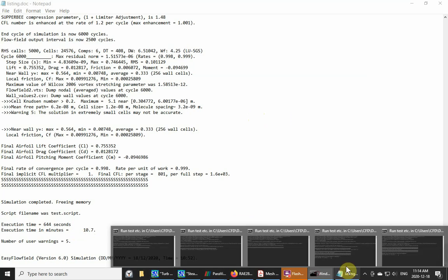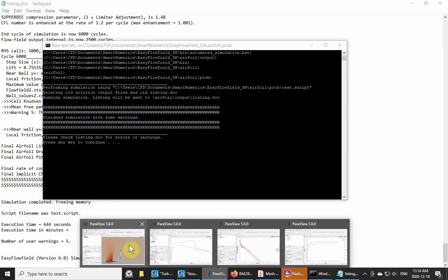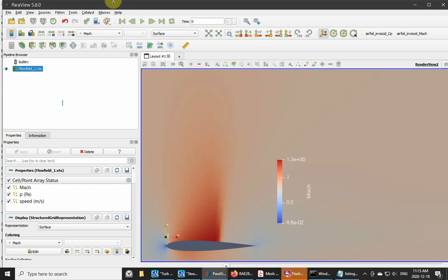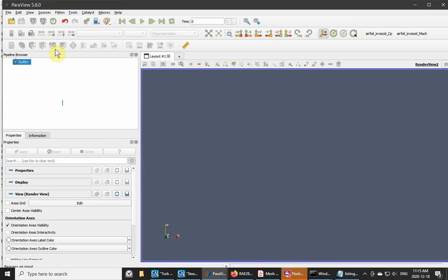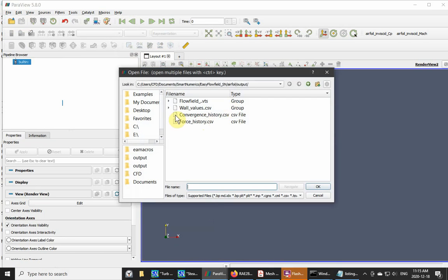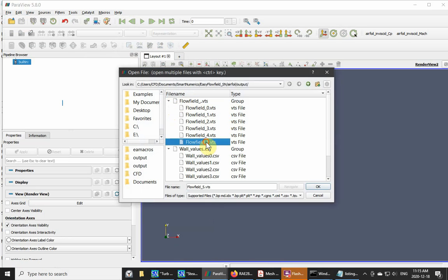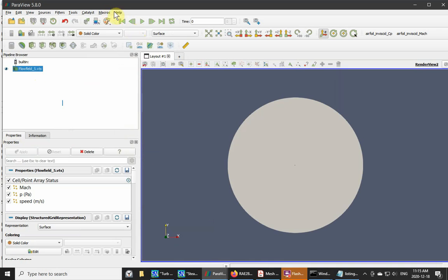Okay, now this simulation will have ended, so I'll then show you the results for the fine grid. First of all, remember how fuzzy this trailing edge shock was. I'll then show the fine grid result. I'll input the appropriate flowfield value, and this is on the grid which has 4 times the number of cells in each direction.